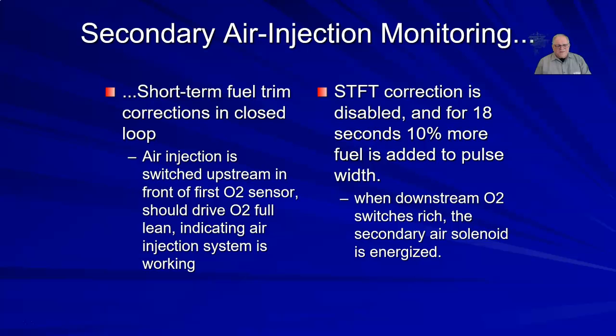Most everything that I've read says this will lower both hydrocarbons and CO. I have a hard time believing that this is going to convert the CO into CO2, because I think we need some sort of catalyst to make that happen. But it's definitely going to decrease your hydrocarbon emissions, finishing the burn in the exhaust manifold. By finishing the burn in the exhaust manifold, it's going to heat the exhaust up faster, it's going to heat the O2 sensor faster, it's going to heat the catalytic converter faster.